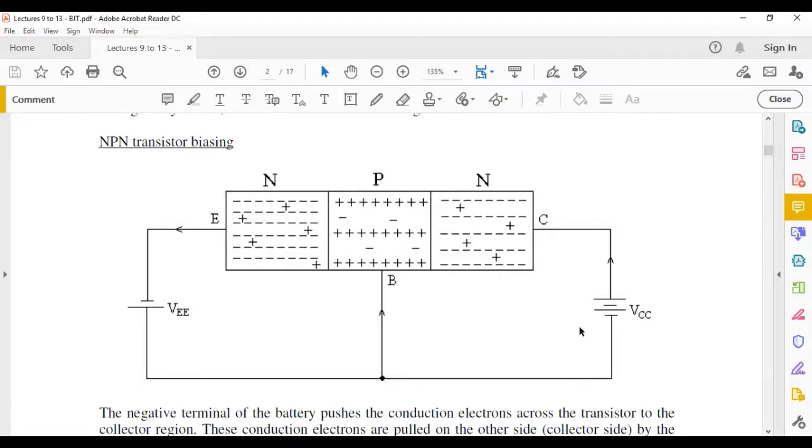Okay. So if you understand these two biasings, the mnemonic comes in. NPN is NPN, so the P there stands for positive. It means the collector and the base have to be more positive than the emitter. For PNP, we found the opposite, it should be more negative. We've seen the logic behind it, but you can't always come to a diagram to understand it. But like I said, in questions where you need to check the biasing, it's a very good trick, a small mnemonic for you. If you have an NPN transistor, the collector and the base would have to be more positive than the emitter. So it's always in comparison to the emitter.